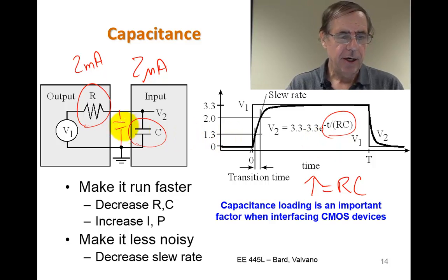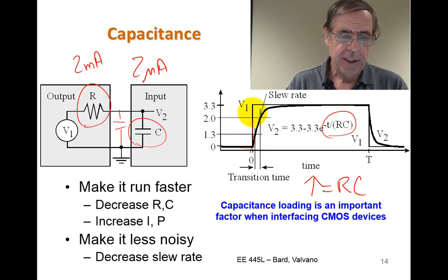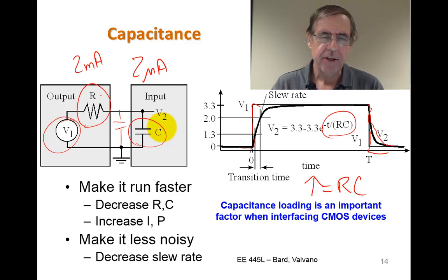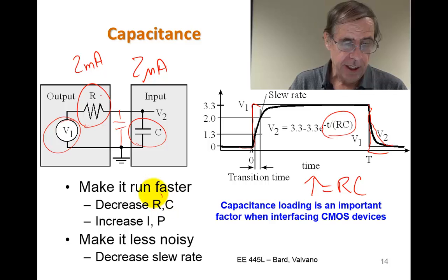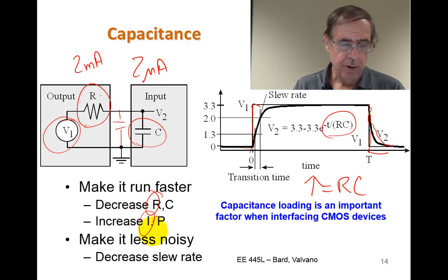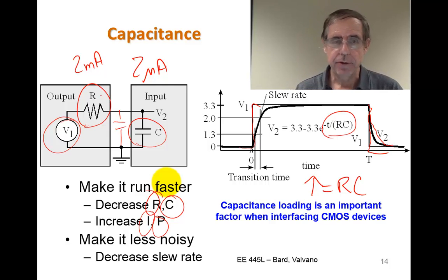And if we look at the RC step response, this is going to be on the test, by the way. If we put in a step voltage here at this input, we will see an exponential response. When I add the step input or I remove the step, we're going to see an exponential response. And that time constant is going to be this R times that C. And those are the parameters that will determine how fast this is. If you want to go faster, you can think of ways to do it. We're going to decrease R, which means we're going to have more current and more power. Or we could figure out better technology, better cabling or whatever to reduce that capacitance.